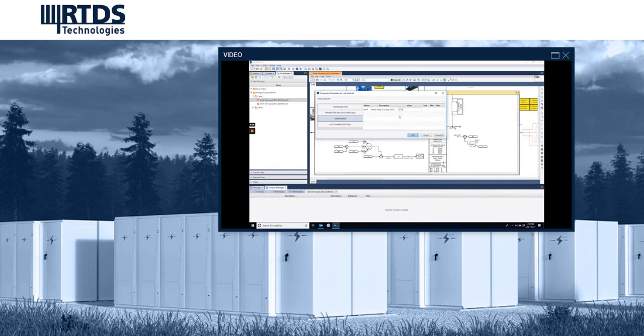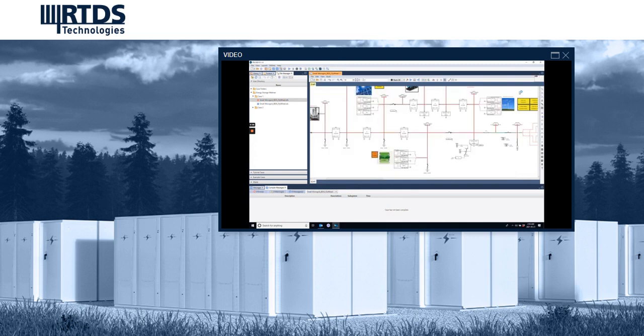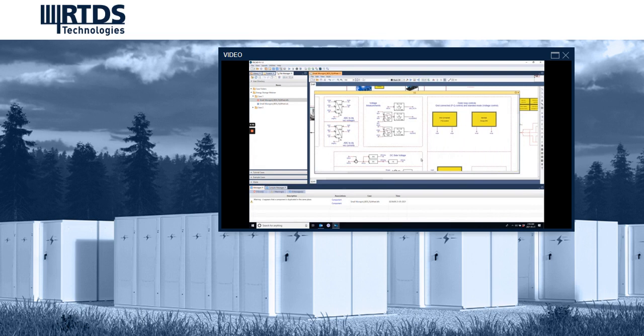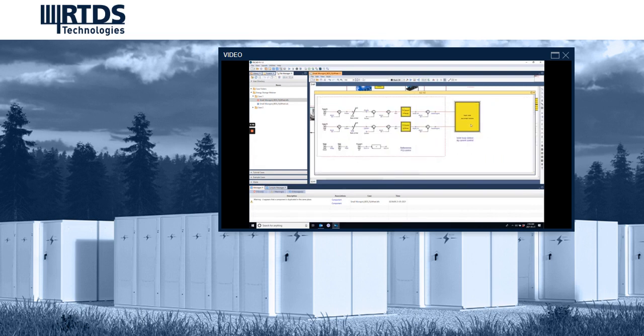The state of charge of the battery can be modeled, and can be monitored in real time. In the battery control system, in grid connected mode, a DQ current control loop in power control is used to control the battery grid currents.